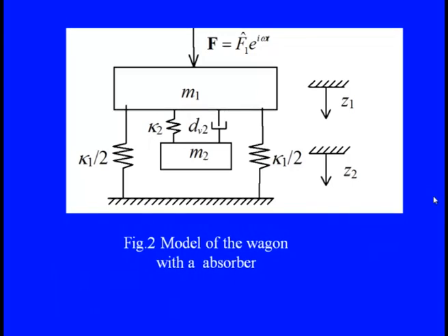Now we would like to put this into the spring mass damper system. If you look at this part, we have the same situation here: the exciting forces F are there. This M1 is the mass we discussed for the wagon part, so this is my entire wagon. This wagon is associated with the two bogies, which are where the suspensions are coming.